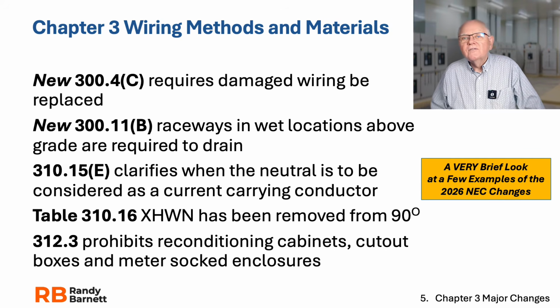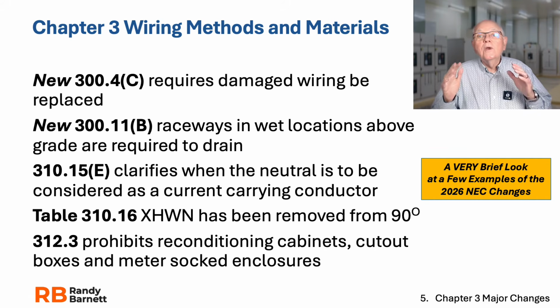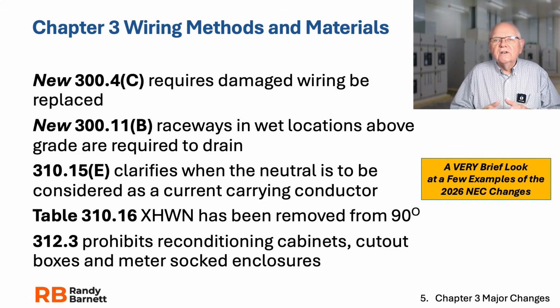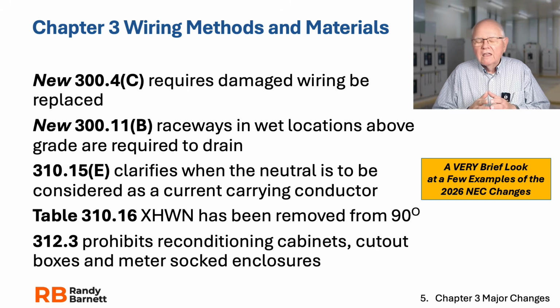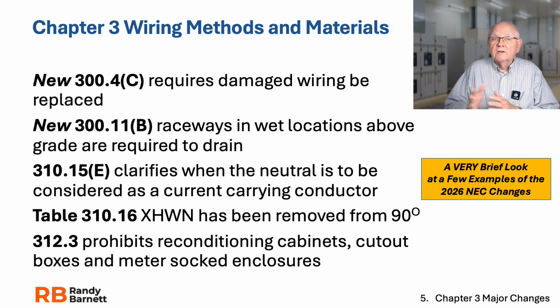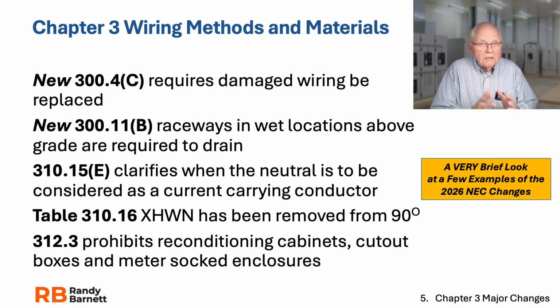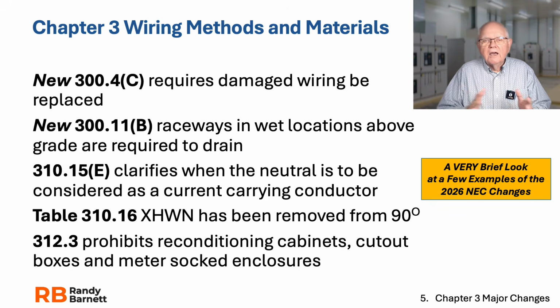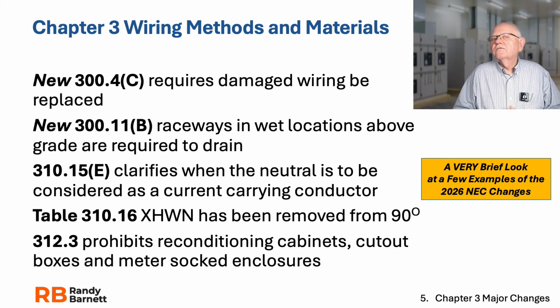310.15E clarifies when the neutral is to be considered a current carrying conductor. Always been interesting in the code book, right? Where we do calculations, is the neutral a current carrying conductor or not? Well, and so on and off we go. Get some more clarification now, 310.15E.